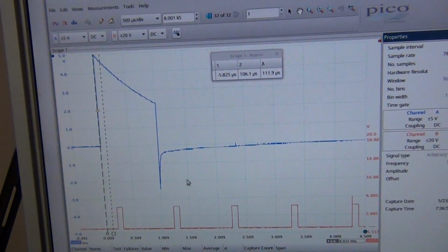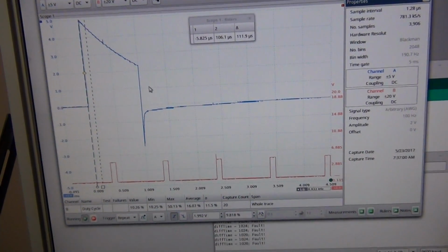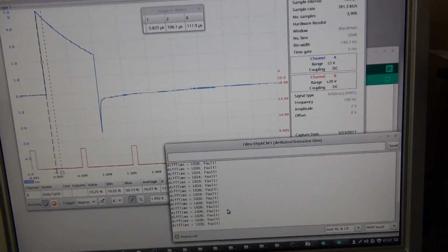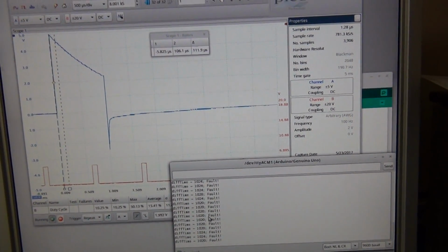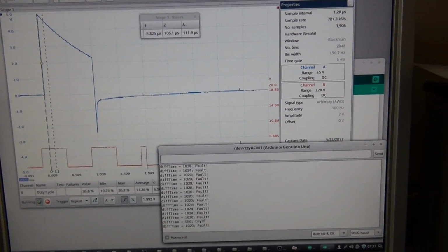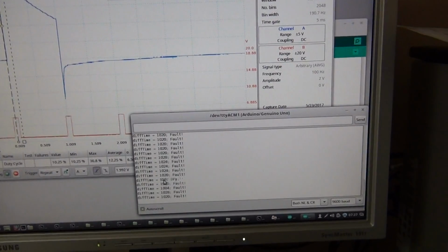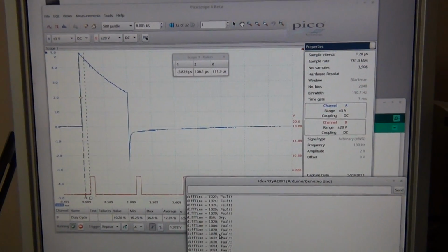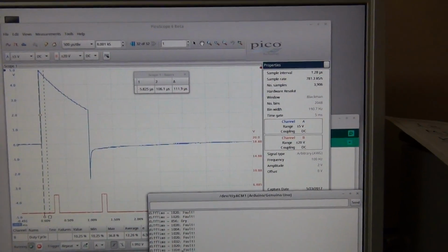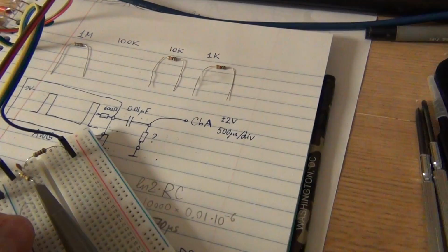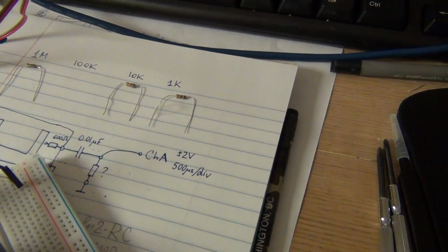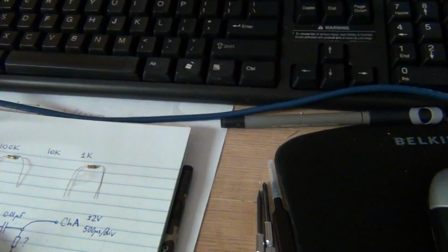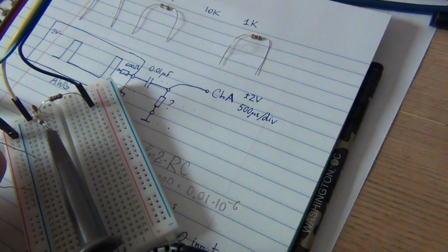Okay, so the pattern changed, and it looks like there is a resistance, but it's not enough to drop the voltage in time, so it's still a fault, though you see that sometimes it's reported that it's dry. It's kind of a borderline case here, that 100K resistor. But now let's lower it even further and replace it with a 10K resistor. And I think it should be more exciting.